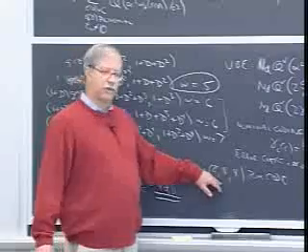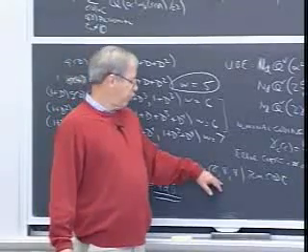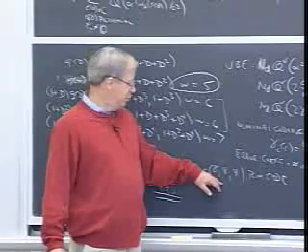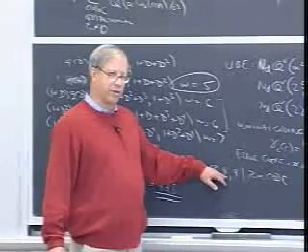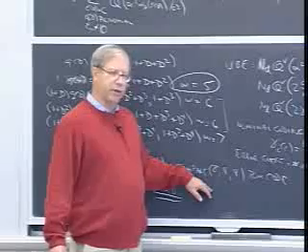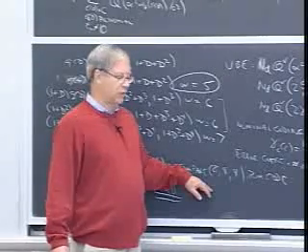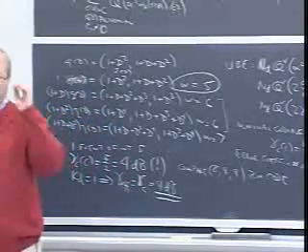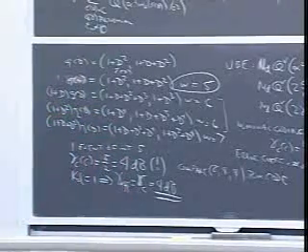And furthermore, it has 14 minimum weight words, which even dividing by 4 to get the number per bit is still a factor of 3. It's still going to cost us another couple of tenths of a dB. Its effective coding gain is only about 2.6 or 2.7 dB.